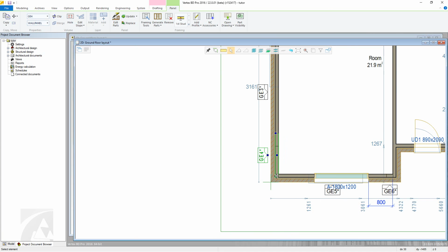If the panel is going into the corner, the overlapping panel can be swapped by right-clicking the grip point and choosing the Flip Corner Connection command. Panels can also be easily split in two using the Cut by Point command from the context-sensitive menu.